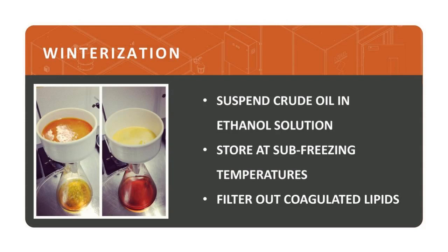For best results, I typically advise that folks do multiple passes. You want to start with a higher micron filter, move to something in the medium range, and then end with your finest filter to really catch every lipid molecule in that solution. Again, the purer the solution that we get, the more lipids we remove from it, the better it's going to be for your final product formulation.